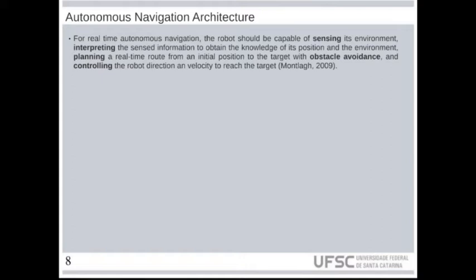As I said, the HD map is the interpreted data ready for autonomous driving, and later planning a road for the car from the initial position to the final target, avoiding obstacles, and of course controlling the actuators, so the actuators follow the planned trajectory. This is what other robots do, and also what the autonomous car must do.